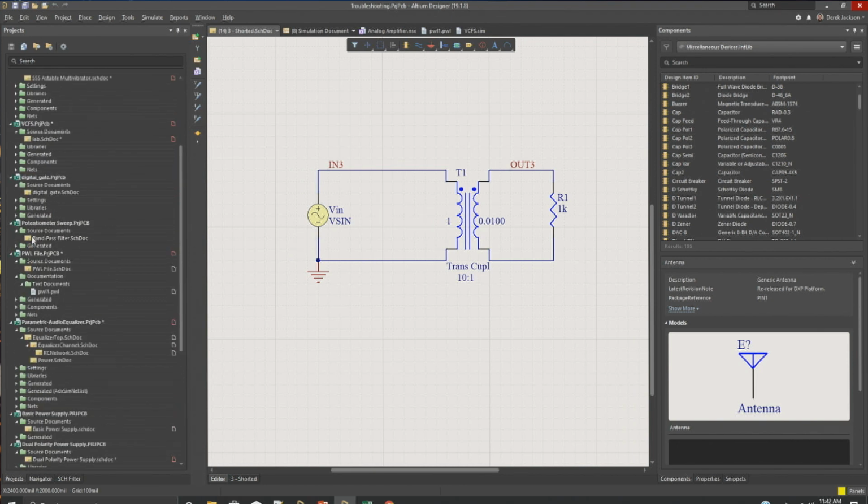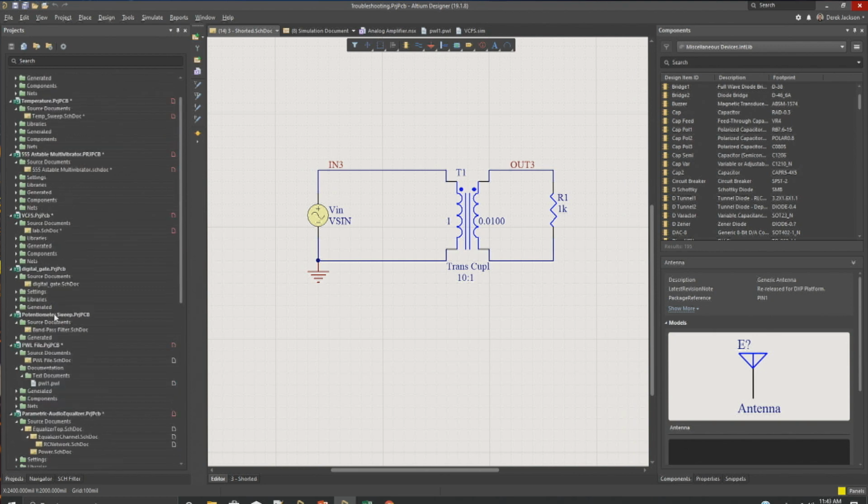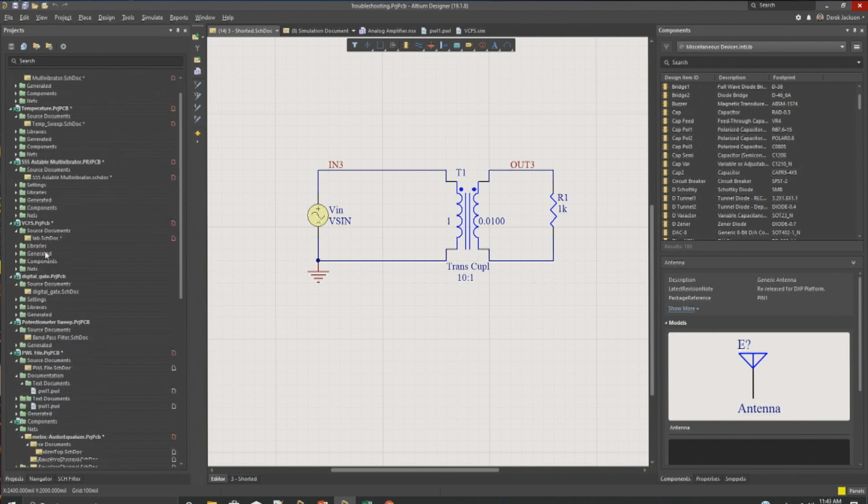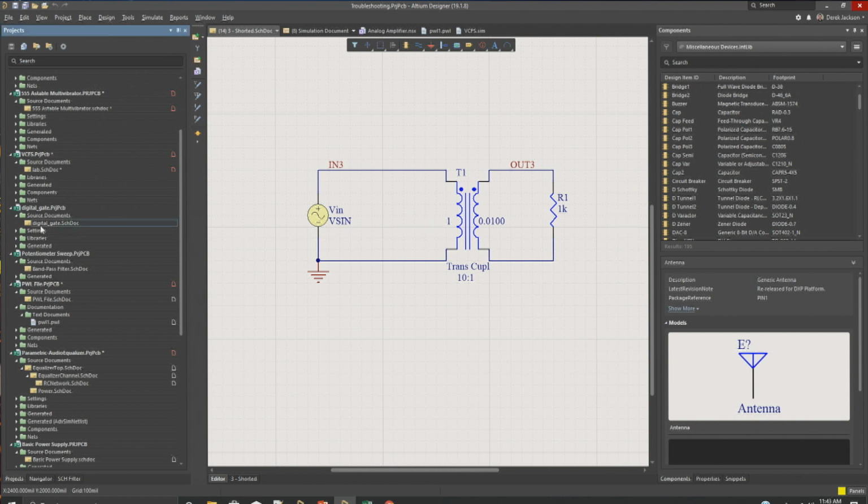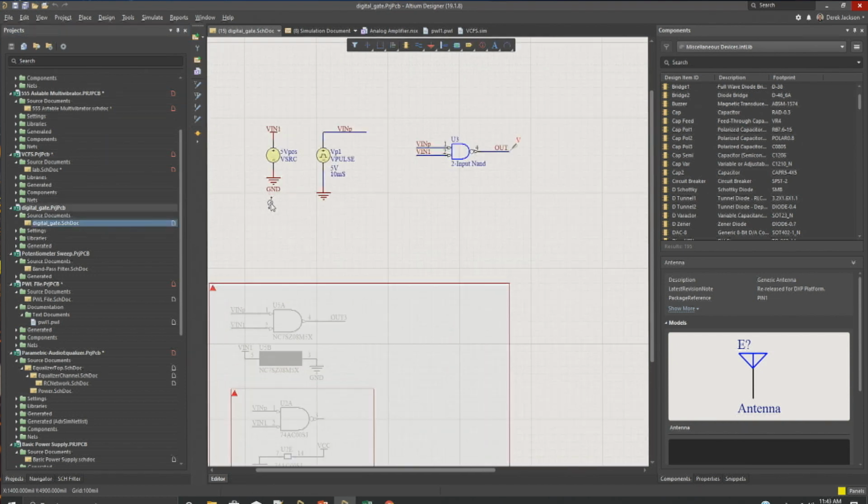Now for the 8.0, currently for our digital components we use a custom language we call digital SimCode, which is a derivative of the old XSpice. It's more of a proprietary digital language, similar to what PSpice did with their digital. XSpice also has its own digital type of modeling. So I'm not sure with 8.0 how they're going to handle the digital part.